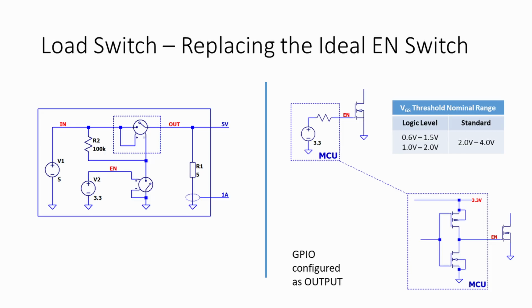MOSFET. Logic level FETs have a threshold voltage that can range from 0.6 to 2 volts or so. Every specific part has a slightly different characteristic, so you have to check the datasheet. The threshold voltage varies quite a bit with parameters like temperature, but for now we're looking at nominal performance. When using the transistor as a switch, you also want to overdrive the threshold voltage to ensure a good turn on. So for these reasons, the variation over temperature and the need for overdrive, FETs with a listed max threshold over 2 volts aren't great choices for 3.3 volt gate drive.